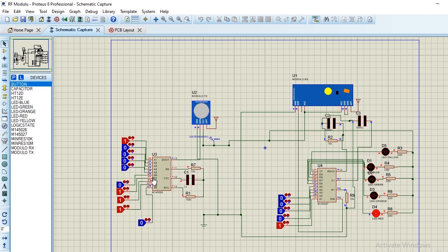So from this is D6 to D9, and we have D6 to D9 too. So once I put D6 high or low, it will also send a signal to the D6. Just like I said, this D6 from the encoder is low, and the D6 of this decoder is, the LED is on, because of the way I connected the LED. So let me turn the rest. So once I make this one low, you will see that D7 is also turning on the LED. Watch, it will also turn the LED. So see, this is the way we send the information.